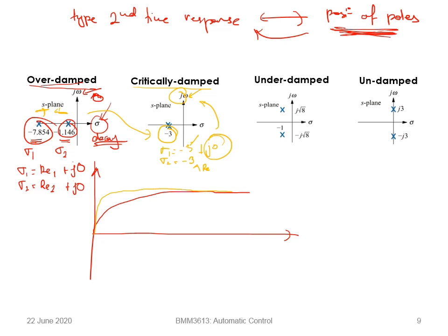But what will happen is that the system will get faster. The system will get more responsive. So it is much faster than an overdamped system. That's why it's called overdamped: you put too much damping on the system, so it is not as responsive as it should be. Now, in yellow, what we have is a critically damped system. It has just the right amount of damping, so that it can respond quickly, but not yet have any undulation or vibration, right?